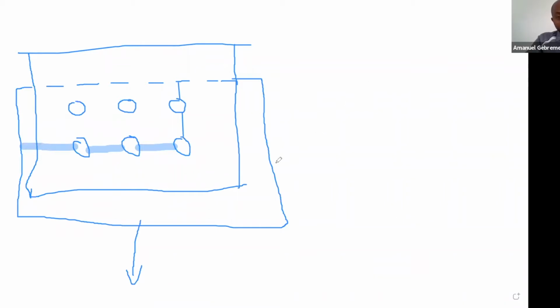And in fact, of course, the symmetrical other side is also possible, where I have a limit state of this type, and I can get rid of these two here, and of this type, especially when this inner plate is actually quite narrow. And these limit states are the ones that almost always control and are, I would say, neglected the majority of the time in checks. So this is what block shear limit state is.